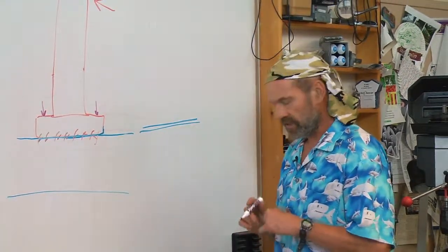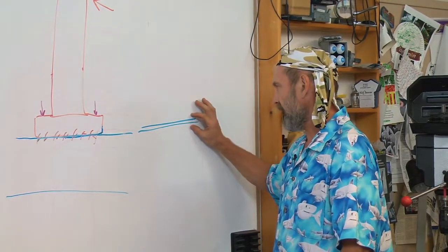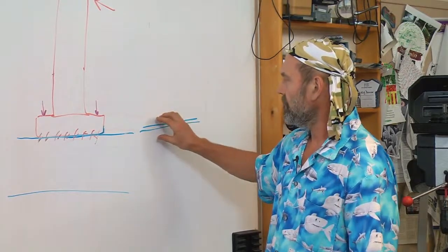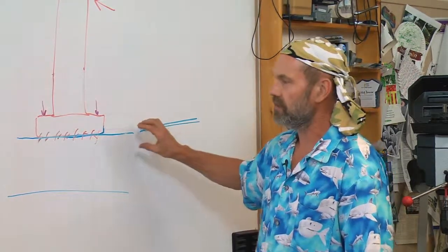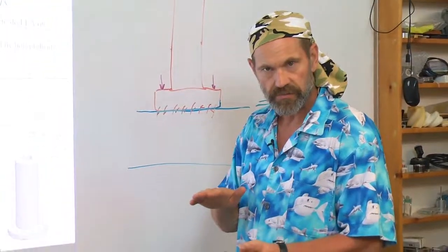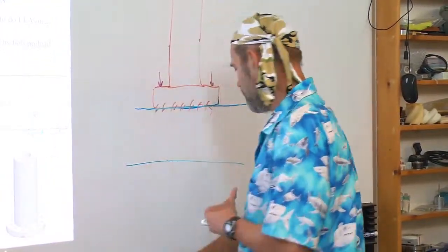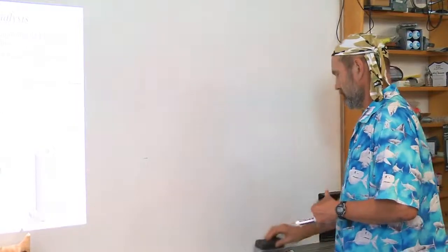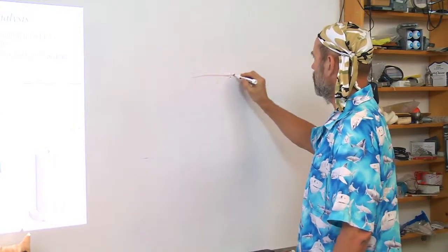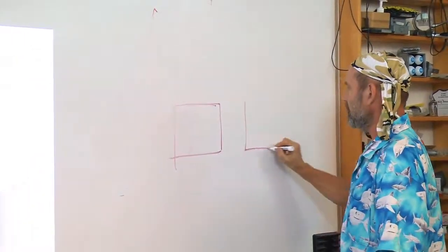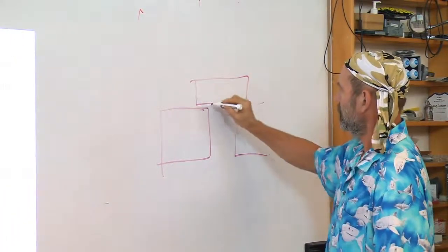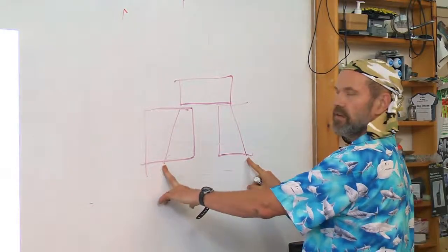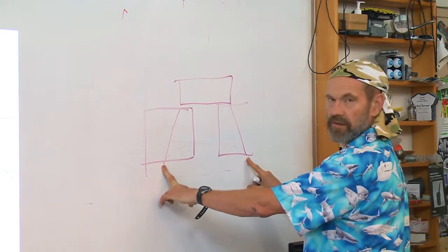If you're running a very simple modeler that won't necessarily do these gap opening elements, this is a nonlinear form of analysis, you can use the notion that I understand what the stress cones are, and when I have my bolted joint in here, if I only have 3 bolts, the stress cones are effectively going to lead to an area of contact that's this circular area under the bolt head.